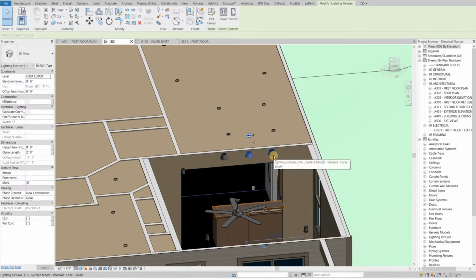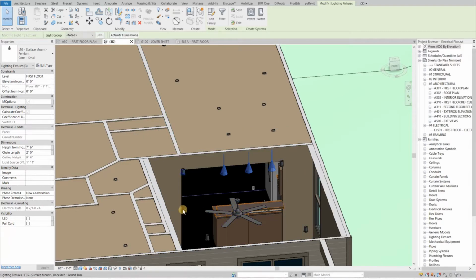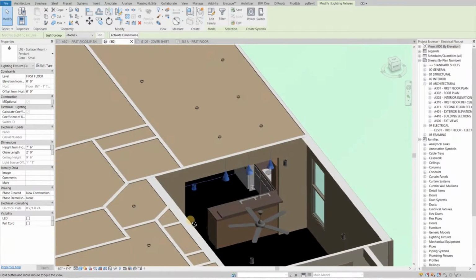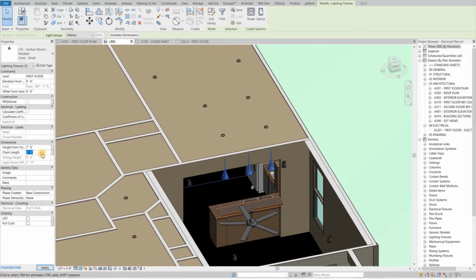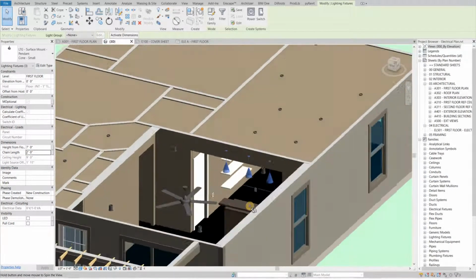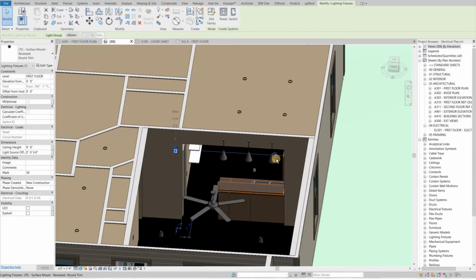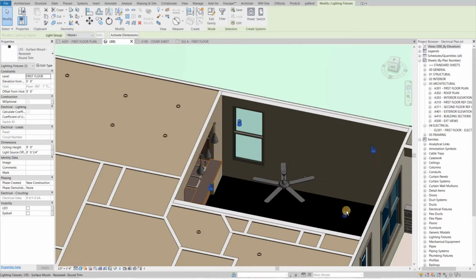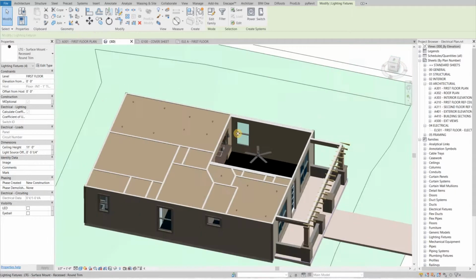Okay, and same for the other three pendant lights here. I can keep it 7, 6, maybe even lower, maybe 7 feet. Let's do 7 feet, and that's 2 feet for the ceiling height. Okay, and these lights, since my ceiling height is higher in this space, I can just raise them to no 11 feet is my maximum height in this space.